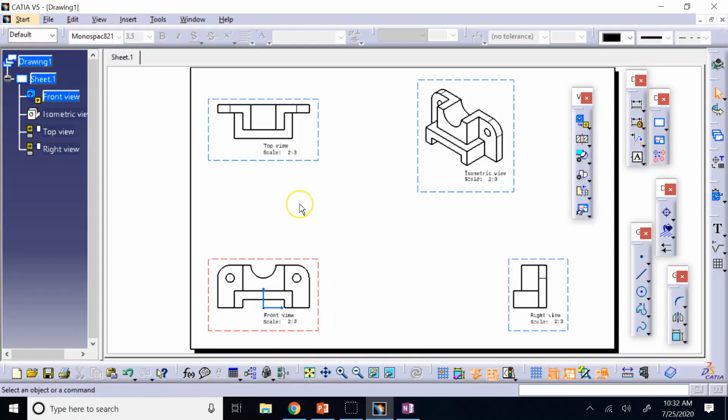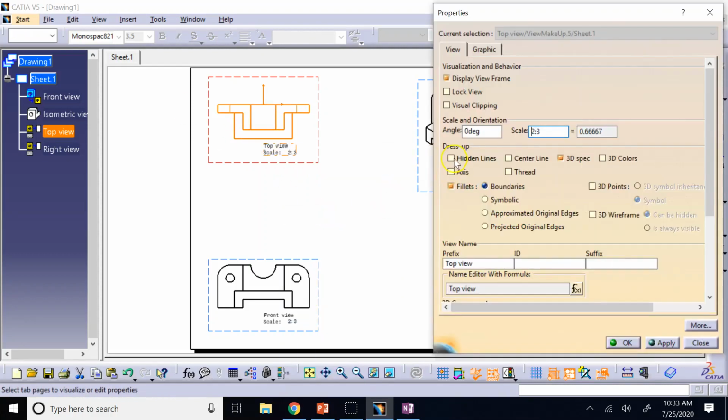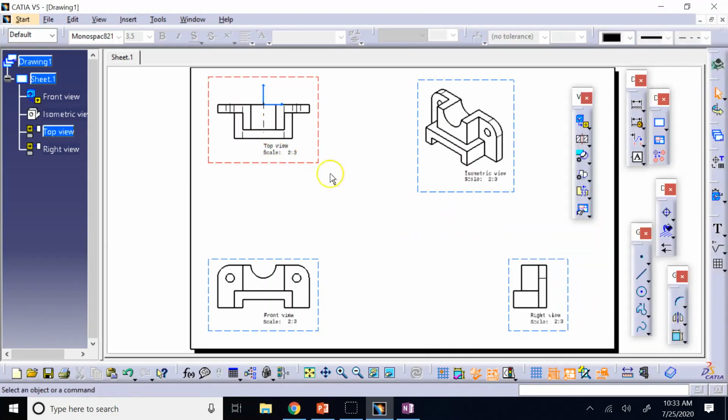Now let's say here I want to cut the top view. So as I said, you have to first make the top view active like that, right? By the way, the top view should be showing your axes and hidden lines, so don't forget. Okay, you have to make sure your top view shows everything, but when you do the section of that, you don't need to show the rest of the detail on the section. So I click on the section, and now this view is activated.